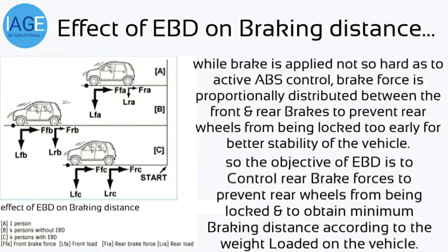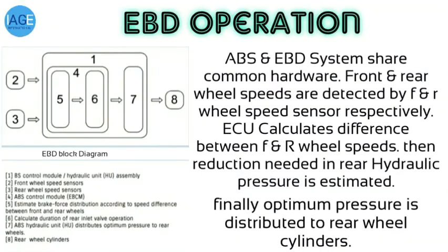Effect of EBD on braking distance. While the brake is applied not so hard as to activate ABS control, brake force is proportionally distributed between front and rear brakes to prevent rear wheels from being locked too early, for better stability of the vehicle. So, the objective of EBD is to control rear brake force to prevent rear wheels from being locked and to obtain minimum braking distance according to the weight loaded on the vehicle.